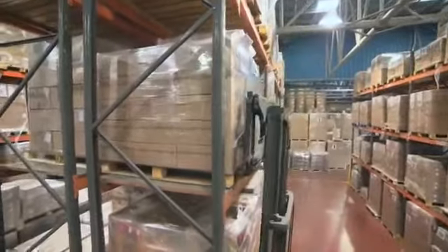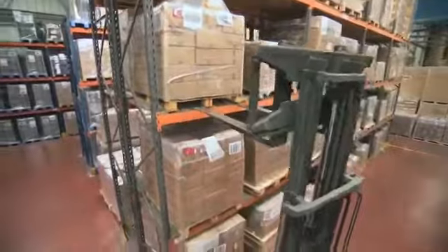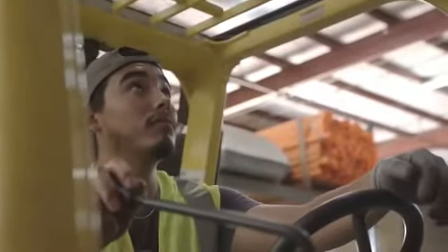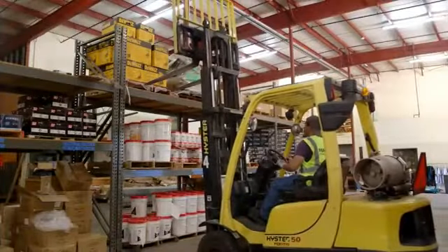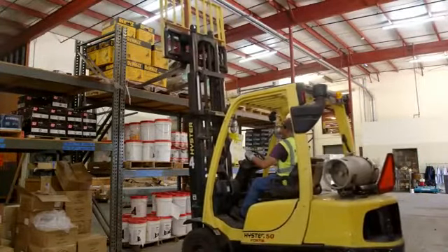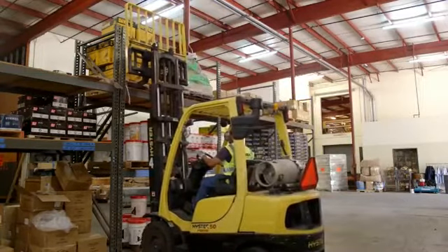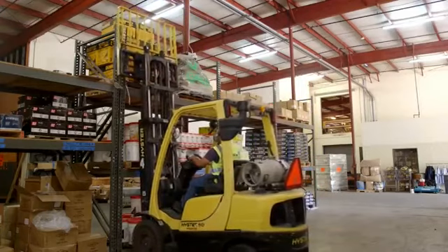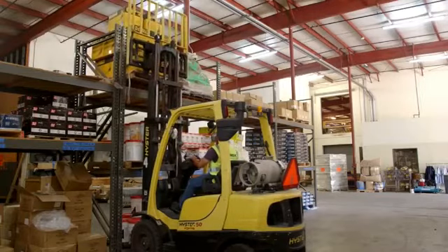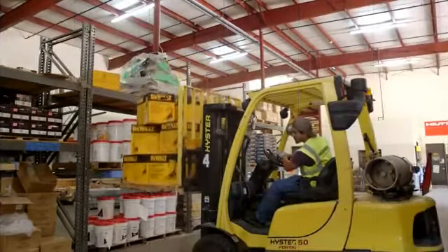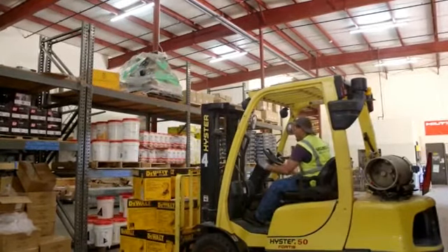Do not tilt forward with the forks elevated except when picking up or depositing a load. Prior to raising the load, make sure there is adequate overhead clearance. While lowering the load, slowly move the truck to approximately 1 foot from the stack. Stop the truck and return the mast to the vertical position. Lower the load to approximately 6 inches from the floor and move forward slowly till the load is in position. Then lower the load completely and back the forks out from underneath the load.